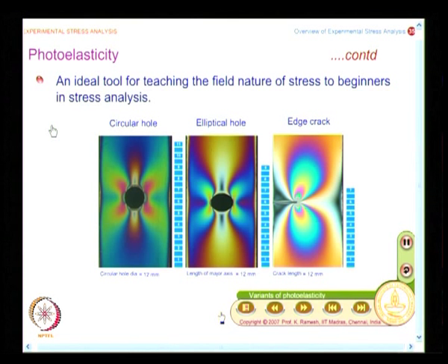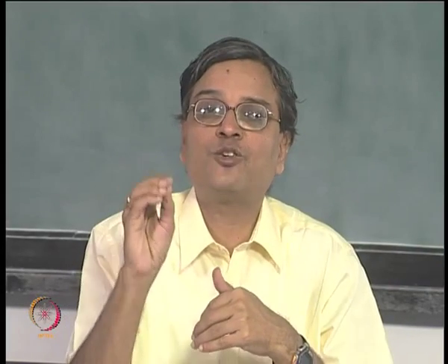And here I must tell you, stress concentration you all know. Right now I have a plate with a circular hole, a plate with an elliptical hole, and a plate with a crack. Now, anybody in engineering will know what stress concentration is, but if you look at the history, mathematicians and stress analysts had an acrimonious debate. Mathematicians used to say an infinite plate with a small hole is equivalent to a plate without a hole, and only with experimental judgment were they convinced that a whole lot of things happen the moment I introduce a stress concentration.